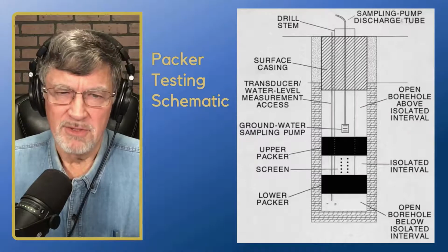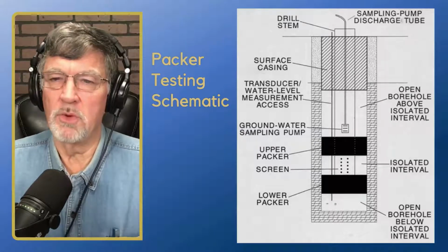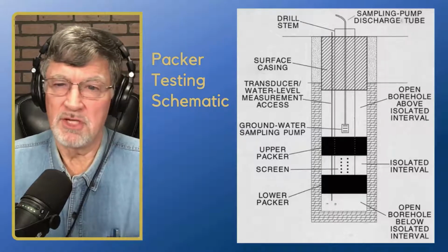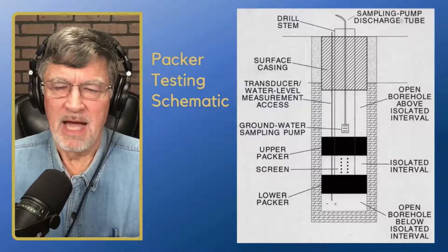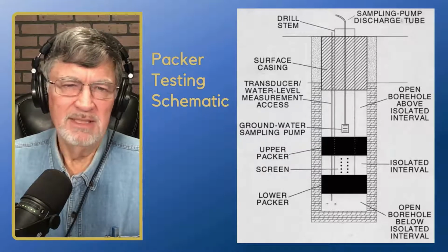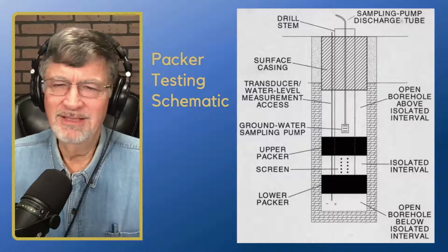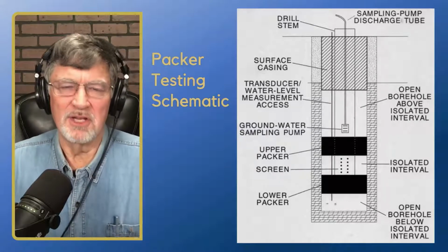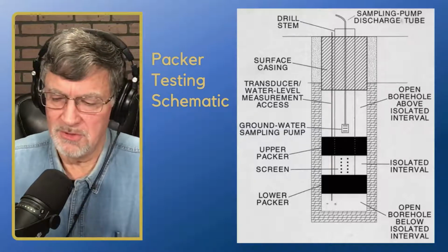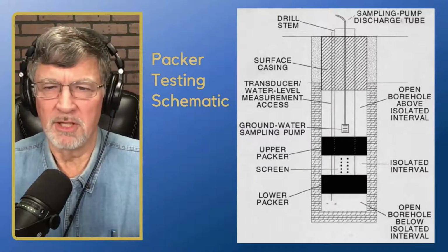If you're trying to do this in an alluvial aquifer, you really want to make sure you have a very stable borehole, and I would start from the bottom up, just to make sure that you're moving your packer out. As you inflate and deflate these things, you may destabilize your hole. So that's something we want to look at.